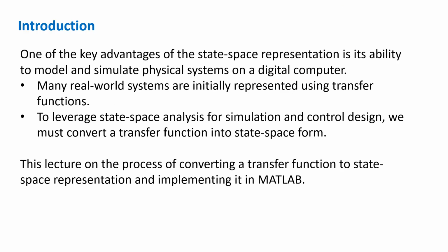One of the key advantages of the state space representation is its ability to model and simulate physical systems on a computer, for example, using software like MATLAB. Many real-world systems are initially represented using transfer functions, and this goes back to the way it was historically done. Honestly, sometimes it's easier to come up with a transfer function. If you're given a differential equation, just take a Laplace transform, and you can quickly come up with a transfer function. However, to leverage state space analysis for simulation and control design, if we have that transfer function, we want to convert it to state space form so we can get it into MATLAB.